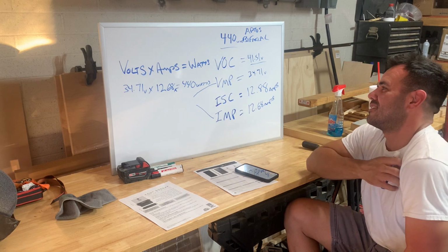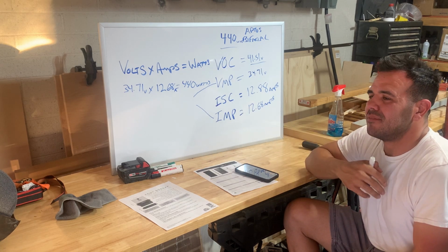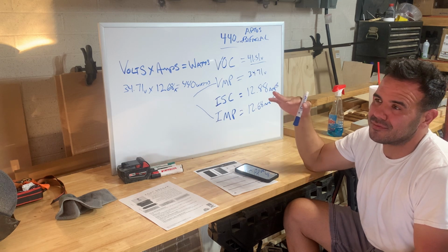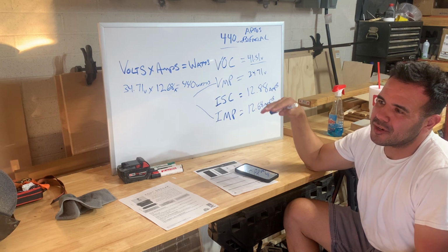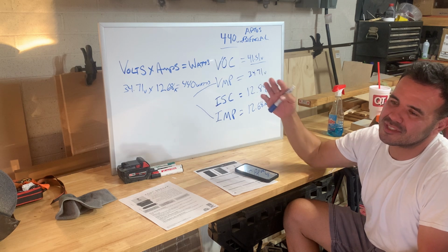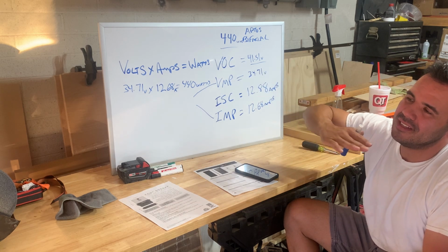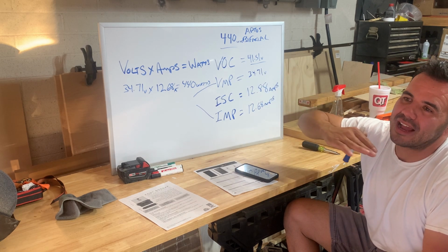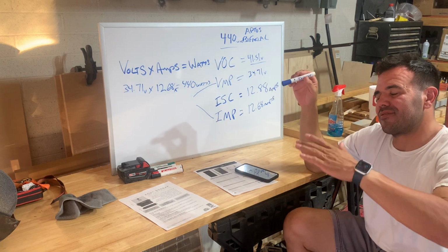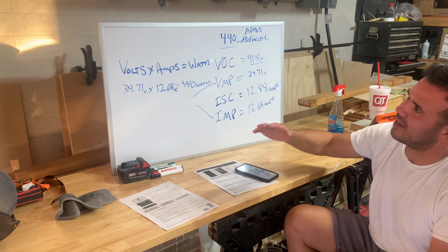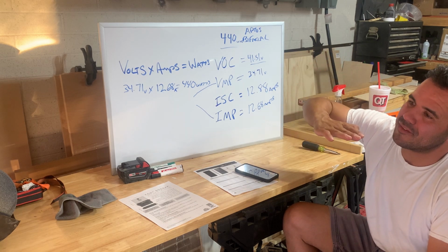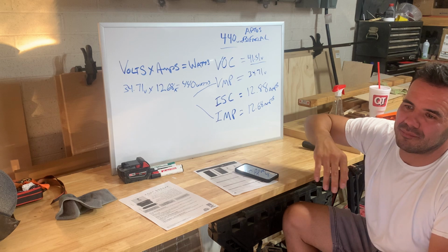And this is another good point to bring up. Depending on where you live, if you live in the northern hemisphere, you're always going to want to have your panels south facing. And in the summertime, the solar panel angle is much better when it's almost flat horizontal. And in the wintertime, the sun comes at a different angle, so your panels are much better off at a higher angle.